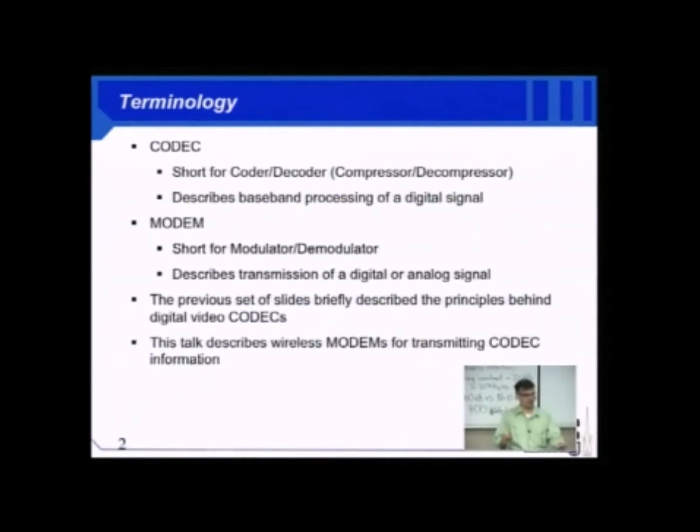Very important, because just like in terrestrial communications, satellite communications are governed by both the FCC and international treaties, and if you are allotted a certain band, you had better stay in that band, or else you make your spectral neighbors very angry. So those 2 pieces of information are necessary, the symbol rate and the pulse shape, and the signal constellation that we use to map bit states to actual symbol states. And that'll all be a little bit clearer by the end of this talk.